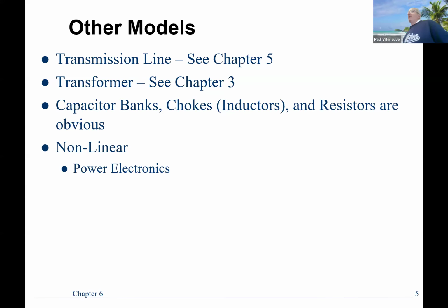So now we can do a representation of our system. We have a model. Now let's actually analyze it. So we're going to do what's called a load flow or power systems analysis. And in fact, the actual result of a load flow, you think, hey, we're going to calculate the flow of load. No, the first outcome of what we're going to be doing is actually calculating bus voltages.